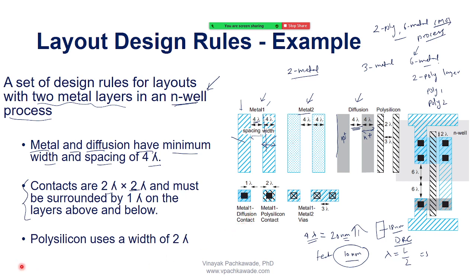So for instance, what is that contact indicating? Let's say I have this P substrate and I have this gate here and I have this active area N plus, this is N plus, and I am having this metal here to make some outside world connection. So I will etch the contacts here, so that diagram is showing this.